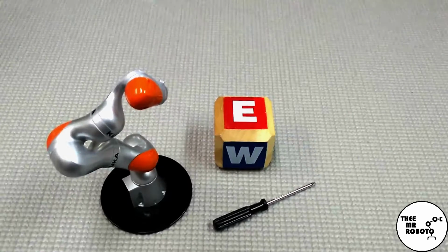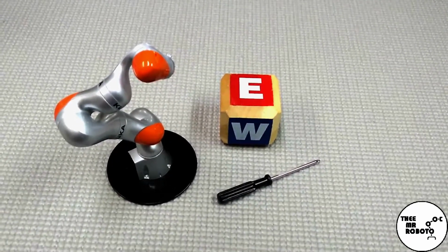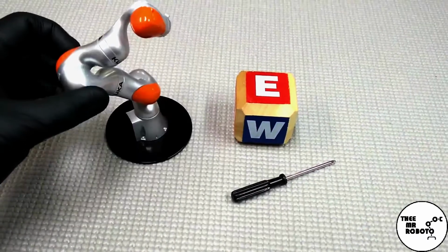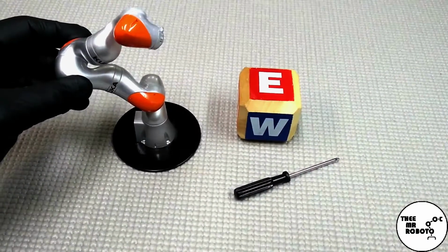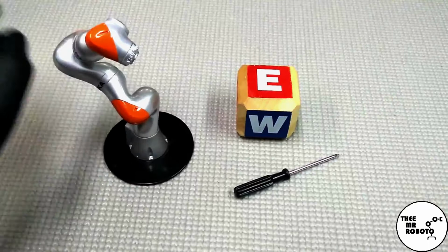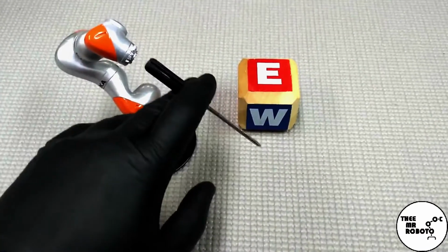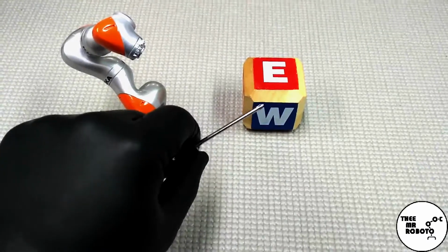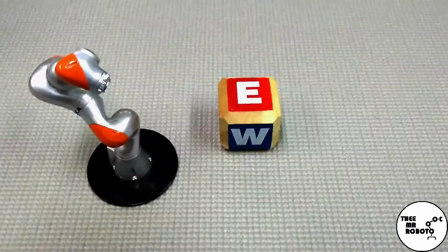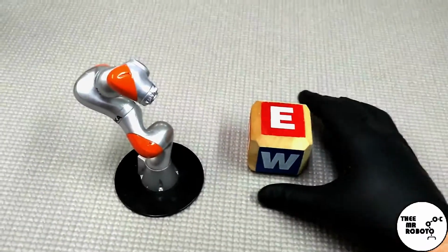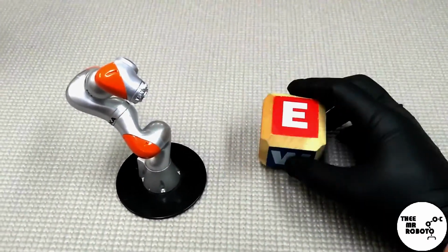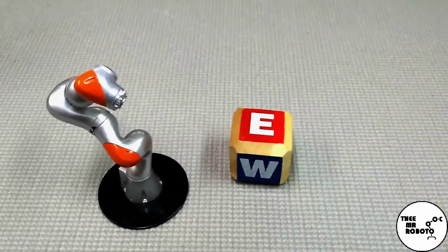Essentially, the first coordinate systems, the native ones, were only in reference to the robot itself. The second set of coordinate systems were based on the dimensions of your end-of-arm tooling. The third is going to be based on whatever the work piece is that you're doing or interacting with.